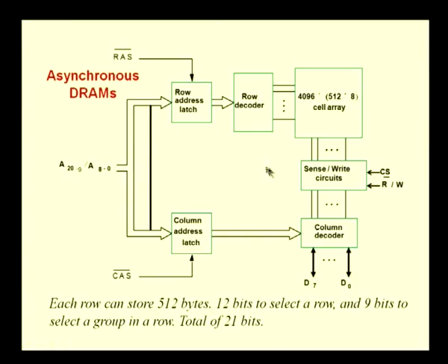So, given that, we are always looking at packing more and more data into the dynamic RAM cells. Now that we have decided that a lot of data is to be stored, how exactly is the data stored? If you want to understand that, we can look at this particular picture here. We have an array of cells, and normally we have different planes of this kind of cell array.